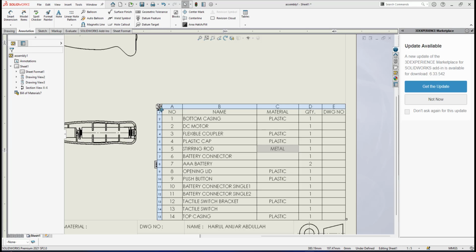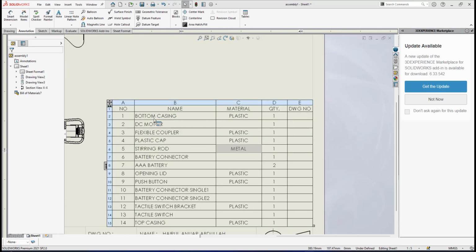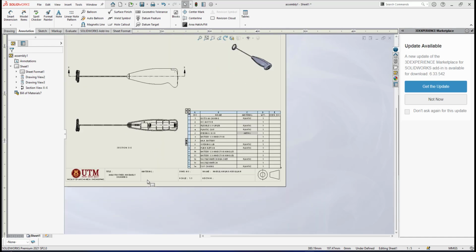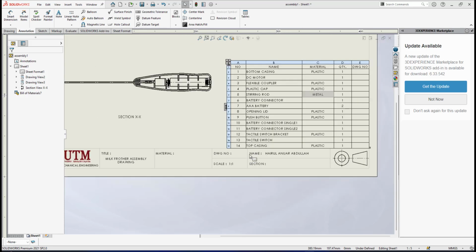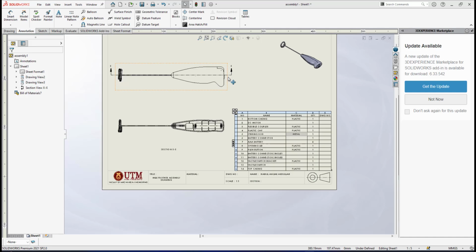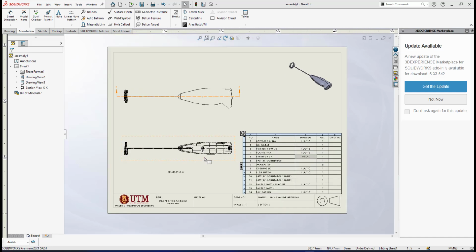In this video I only show the assembly drawing, and maybe the second part will show the exploded drawing. So drawing numbers only start for the detailed drawing of each component; I don't have to put a drawing number for the assembly drawing and exploded view drawing. The next thing to do, since I already have the BOM, is to show how I will do balloons.